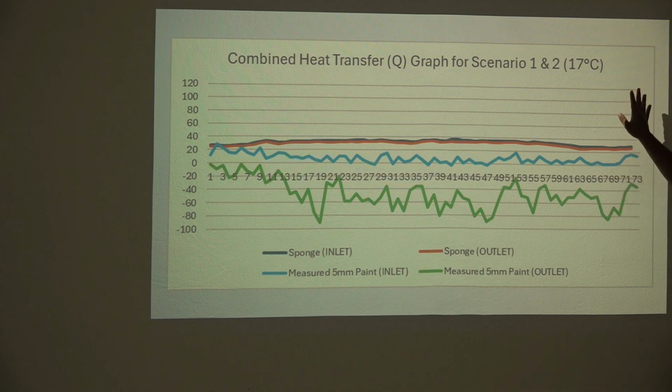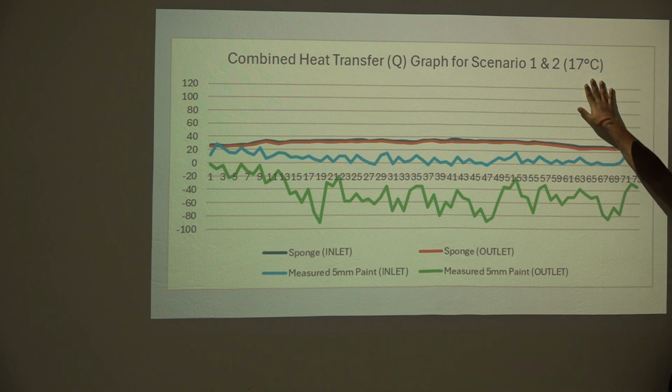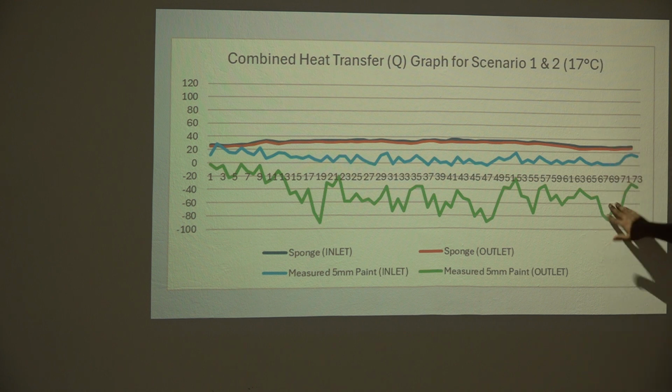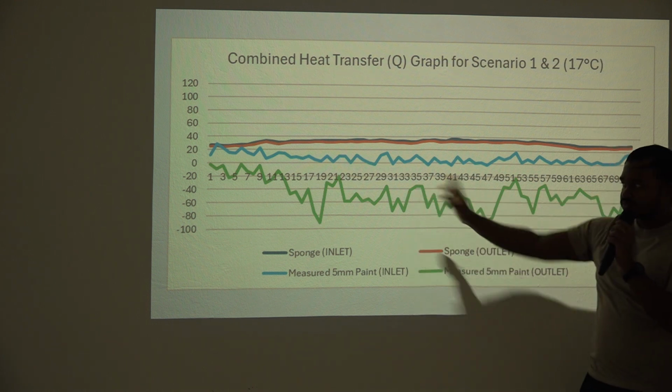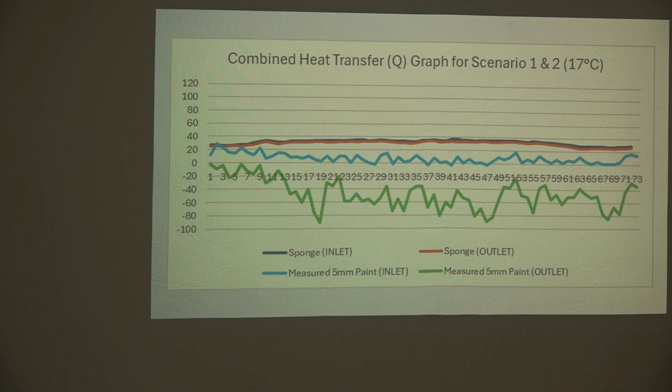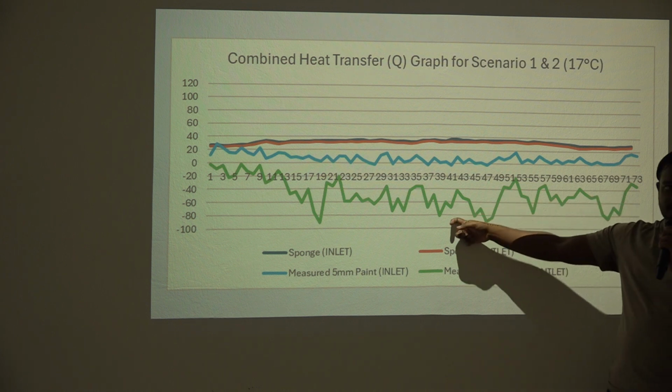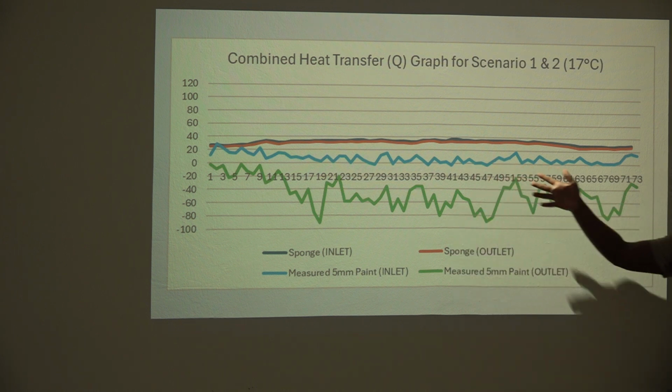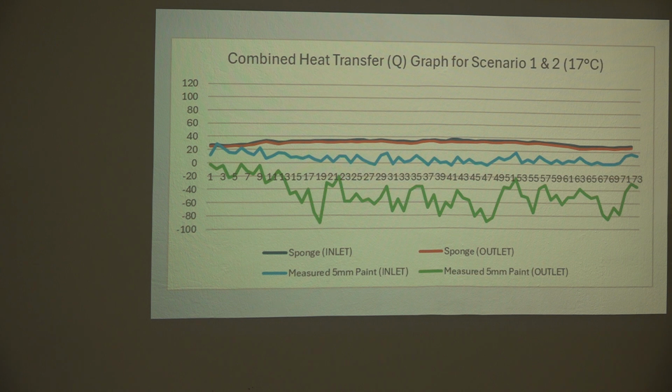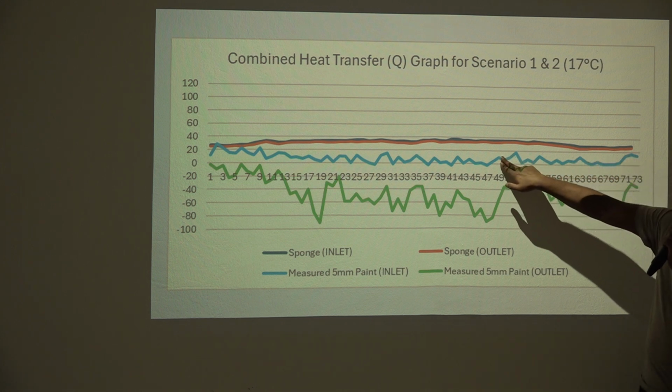So our AC system, we set at 5 different temperatures, we collected 5 different sets. First we set 70 degrees, and as you can tell, this one is in the negative zone, which is not quite optimal. It might seem optimal because we want to really see it, but this is actually the outlet pipe, which, as mentioned before in the AC system, is actually carrying in vapor. So we don't want the vapor to condense in the pipe itself, if not it will destroy the compressor when you put it in. So this is not really optimal, but the other pipe is actually doing pretty good.